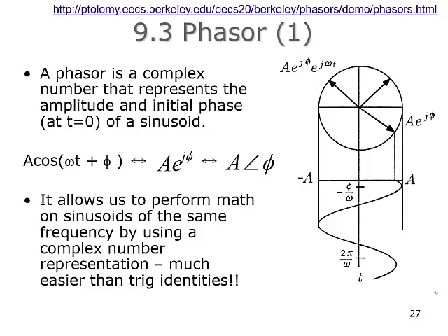We just introduced phasors on Monday briefly, and we showed how, if you think of that vector, which represents a complex number as an amplitude and a phase, as representing the phase of a sinusoid, then you can imagine that vector is rotating around the origin with time. We find it really convenient to pull out the amplitude and the initial phase and stick that in a complex number, which represents the location in the complex plane where the sinusoid started off at time 0.